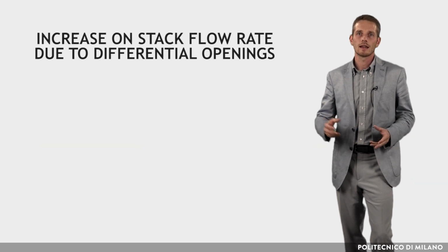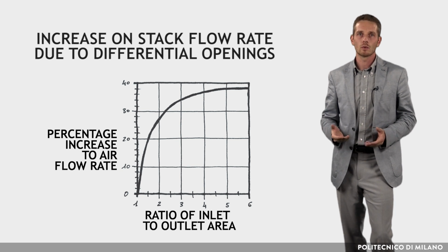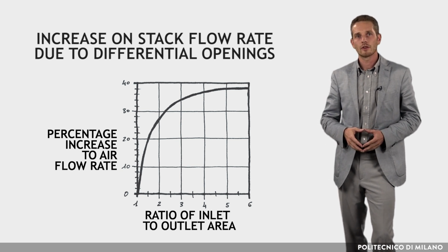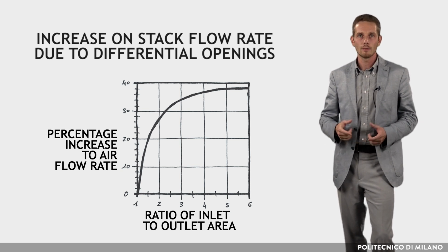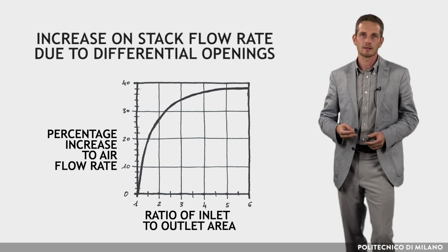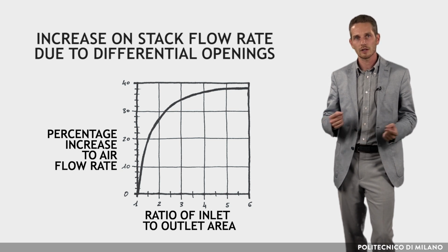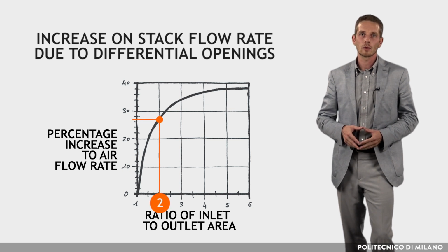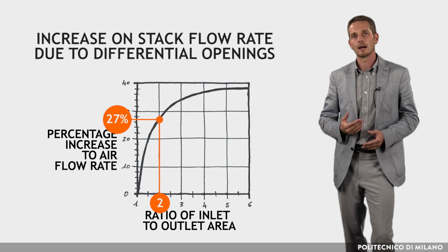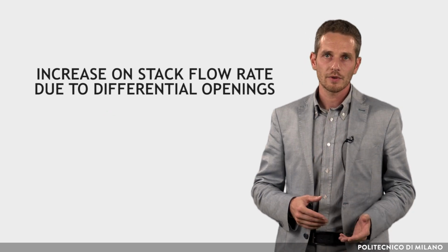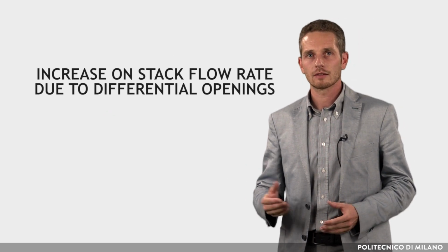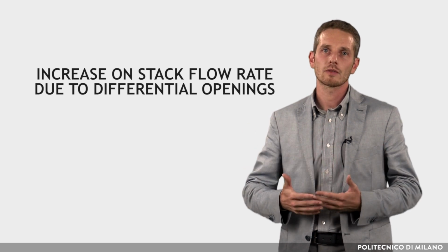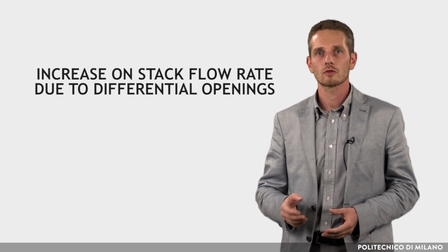If the inlet and outlet areas are not equal, the airflow is first determined using the smallest of the two areas, and then, according to the ratio between them, the percentage of the flow increase can be provided by a graph. Where appropriate, the same correction factors for louvers and fly screens as for cross ventilation should be applied.